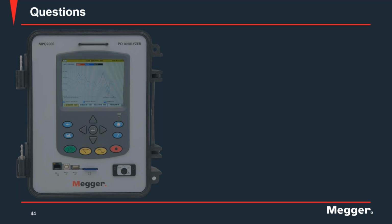All right, let's jump into the Q&A session. Our first question I'm going to be directing to Mr. Andrew Sagl. Andy, we get a lot of DC bus overvoltage even when equipment is not running. Filter seems to help, but we still get them when the filter is on. Where would you look for power quality issues? The transformer is already tapped down a little, but it hasn't helped.